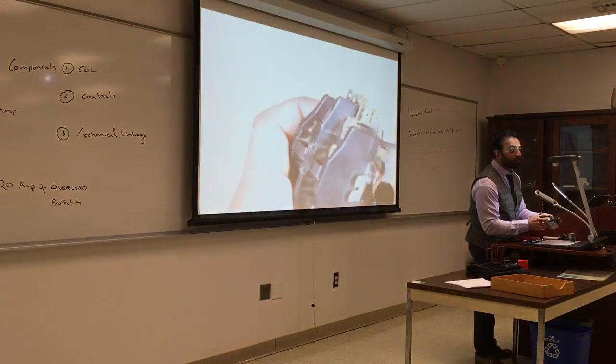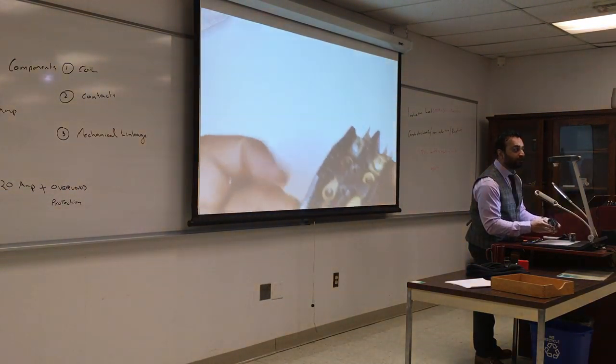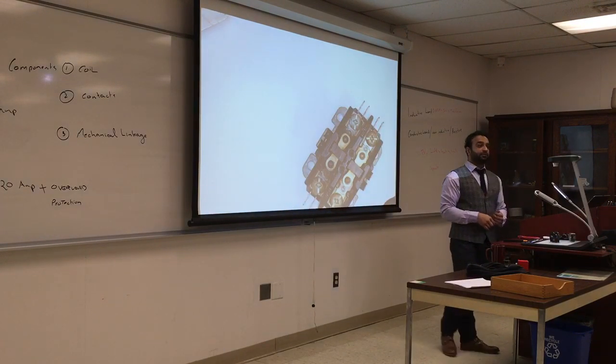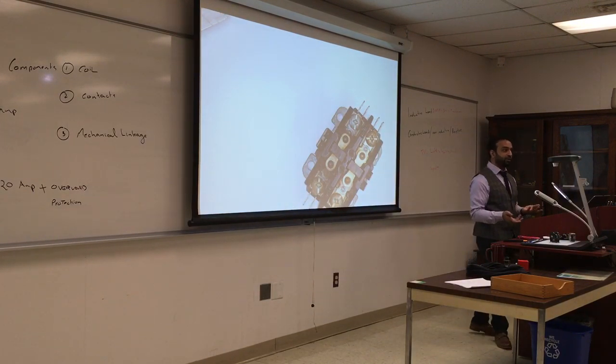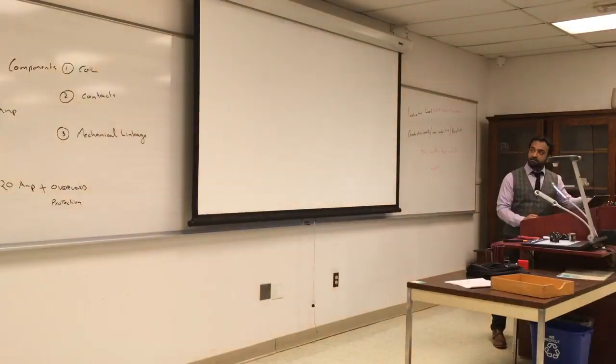Again, the coil, you always have to make sure that the coil connects to the right voltage, otherwise it will burn. A lot of times people connect the coil when it's 24 to 120, and this is how you burn the board.